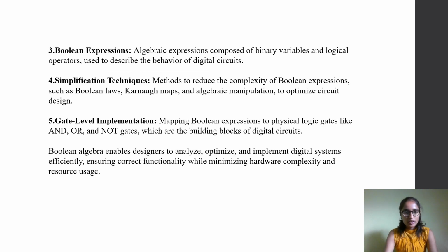Boolean expressions: algebraic expressions composed of binary variables and logical operators used to describe the behavior of digital circuits. Simplification techniques: methods to reduce the complexity of Boolean expressions such as Boolean laws, K-maps, and algebraic manipulation to optimize circuit design. Gate-level implementation: mapping Boolean expressions to physical logic gates like AND, OR, and NOT gates, which are the building blocks of digital circuits.